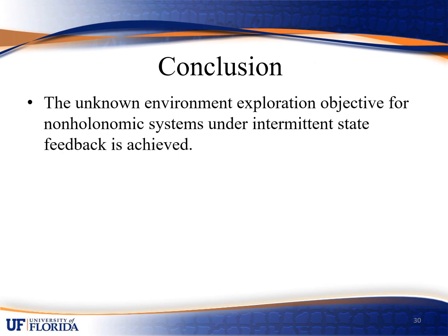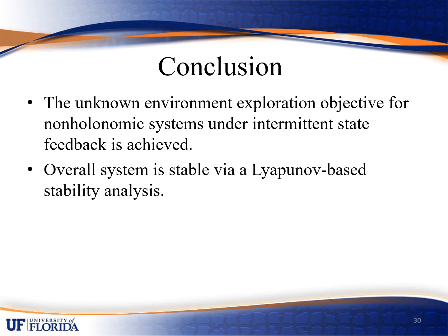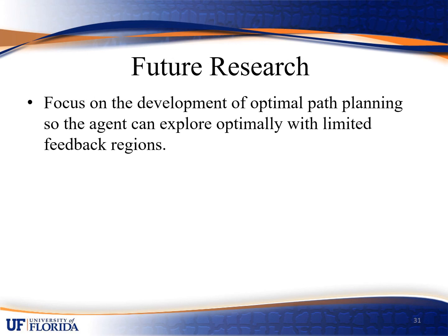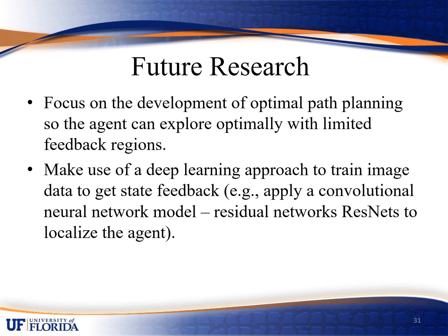To summarize the presentation, we have shown that the unknown environment exploration objective for non-holonomic systems under intermittent state feedback is achieved. The overall system is stable via a Lyapunov-based stability analysis, and Zeno behavior is excluded. The future research of this topic will focus on the development of optimal path planning, so the agent can explore optimally with limited feedback regions. In addition to that, we will incorporate a deep learning approach to train image data to get state feedback.